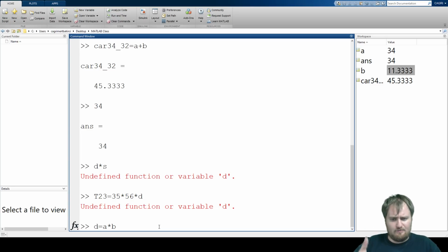And as you can see, let me teach you something else here. Whenever I type a line of code, it spits the result back at me. I might not want to see it. Like, this is an intermediary step. Let's say in my longer calculation, I don't want to see it. Don't show that to me again. So if you don't want to see the result of one of your codes, you just put a semicolon. And semicolon is one of the most important things in this lab.